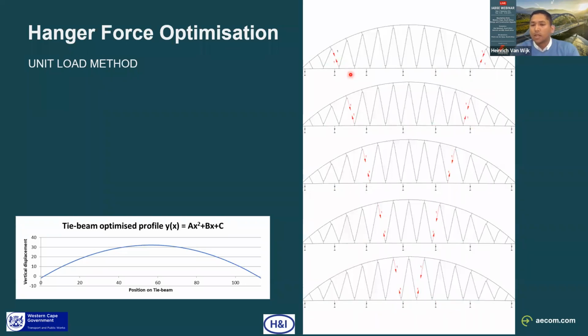And once you've got some data, which is, I think, 12 sets of deformations. The way your forward building FEM model works is that it sums up those construction stages, so that at the end of the cable installation stages, your deck profile should look something like this target profile. But because we've used an arbitrary number, 1000 kilonewtons, obviously, when you sum up your first set of deformations, you would have a poor deck profile.